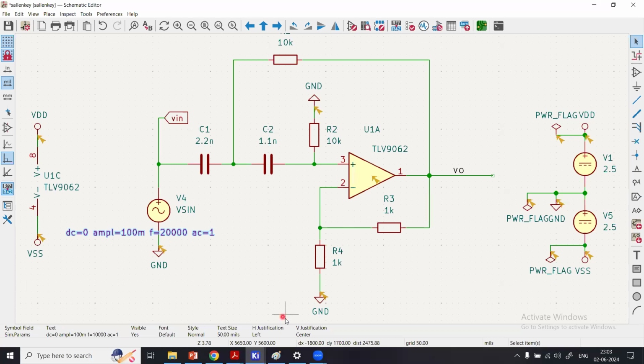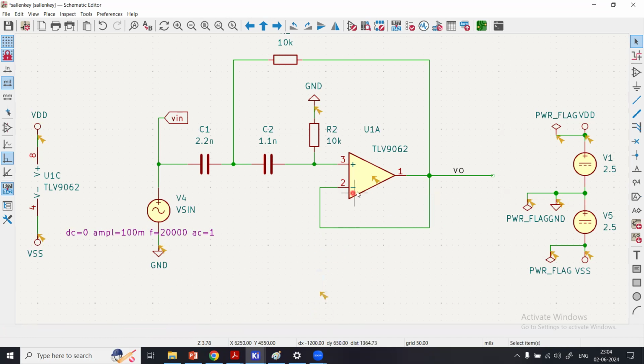What if I don't want an amplification gain, I just want to use the op-amp as a buffer. With that, I will see the frequency response and the time domain response. So I will just click this and remove this, and that is what I want. I'm connecting the output back to the input, the negative pin. So using it as a voltage follower, output voltage will be the voltage at the positive input. So this is just a buffer.